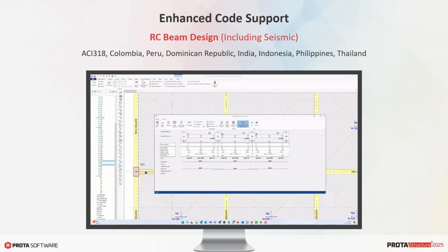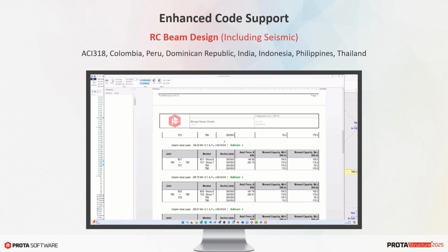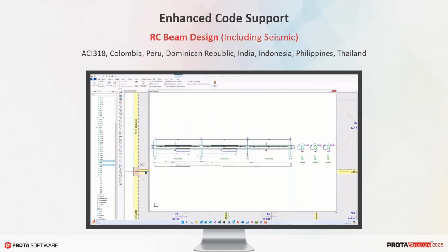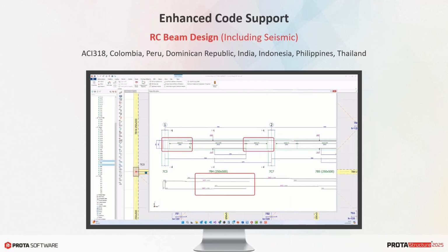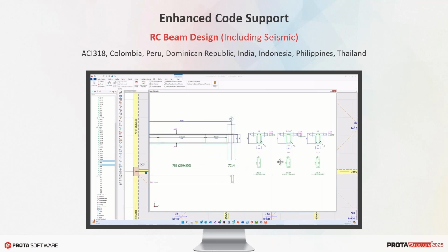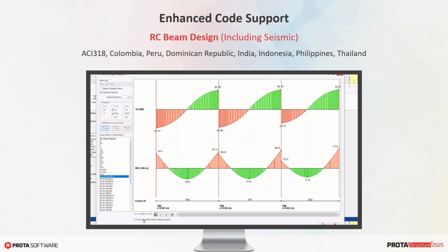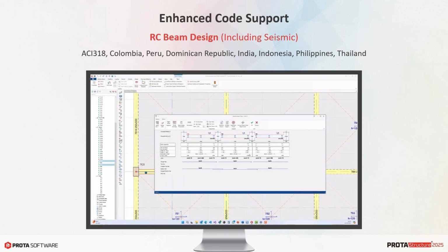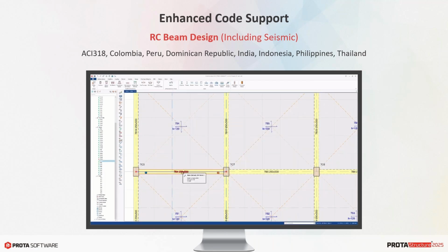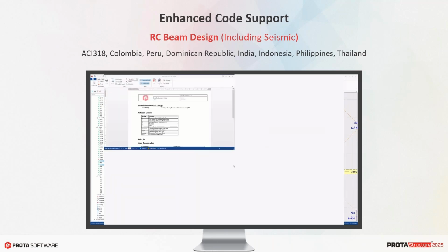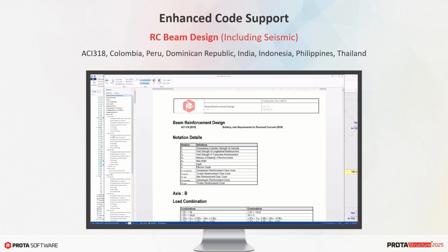Again, in addition to the member checks, seismic checks, and non-seismic checks, we provide detailed reports on strong column, weak beam checks, and joint shear checks to ensure ductility in a specific joint. And these new additions and improvements are sitting on top of the existing global building checks, as I mentioned, such as irregularity checks, relative drift checks, and non-structural member checks, etc. So ProtaStructure is much more complete in the sense of non-seismic and seismic design checks in this new version.